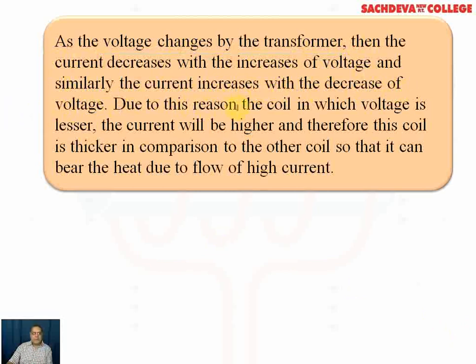Due to this reason, the coil in which voltage is lesser, the current will be higher, and similarly, this coil is thicker in comparison to the other coil so that it can bear the heat due to the flow of high current.